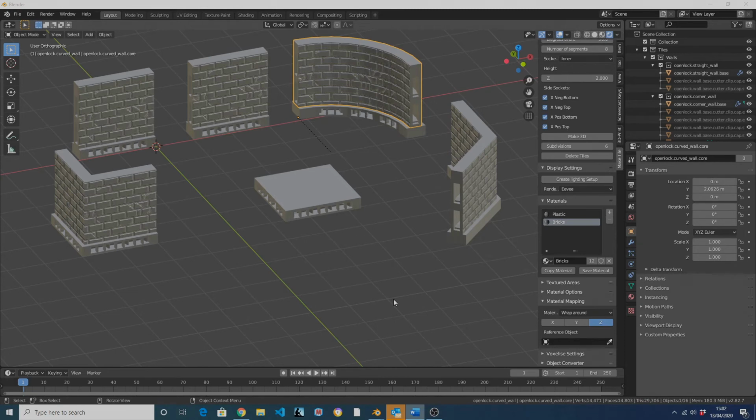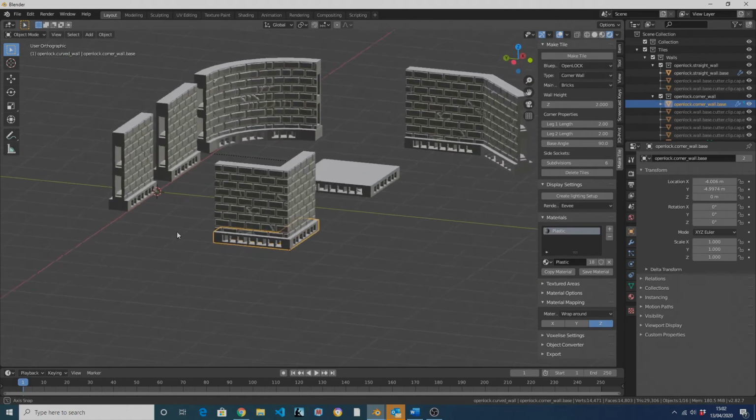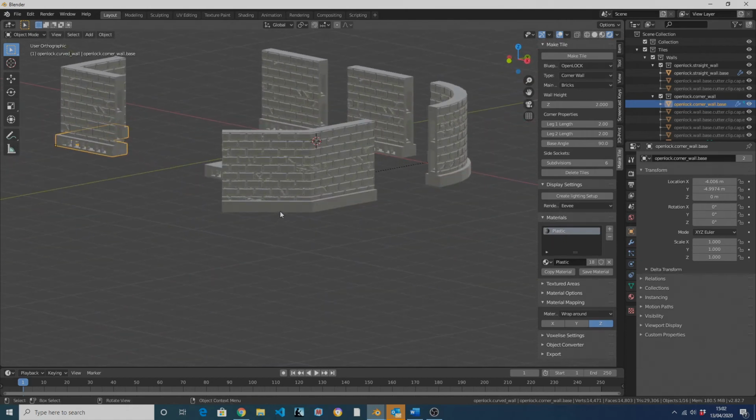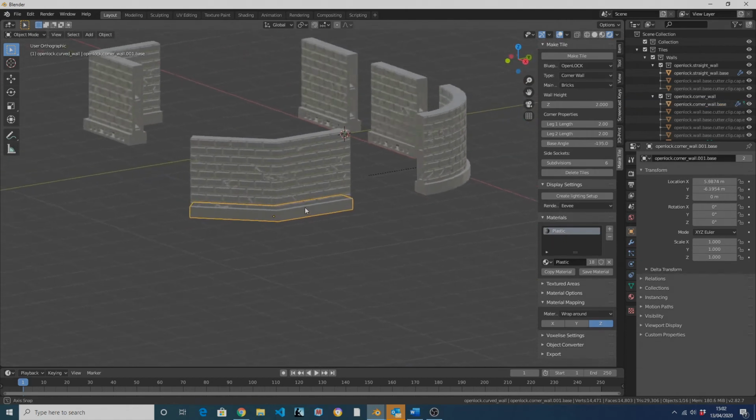By default, this material uses a type of texture mapping that works based on wrapping a texture around a reference vector, which by default in this case corresponds to the world z-axis. That means if I create a corner wall, whatever the base angle, the texture will display correctly. However, it means that there is no texture displayed on the floor tiles.